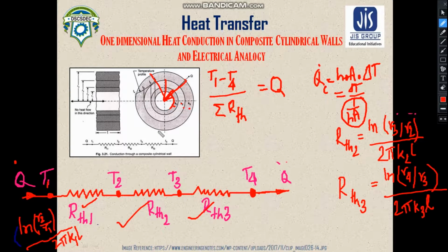So that depends on the problem. It would be mentioned in the problem the nature of the fluid motion, where the fluid motion is carrying on, and how the convection is carried out. So the basic concept is that if there is heat transfer, then there is thermal resistance. And if you want to find out the heat transfer in terms of the innermost cylinder temperature and the outermost cylinder temperature, then you have to add up all the resistances.